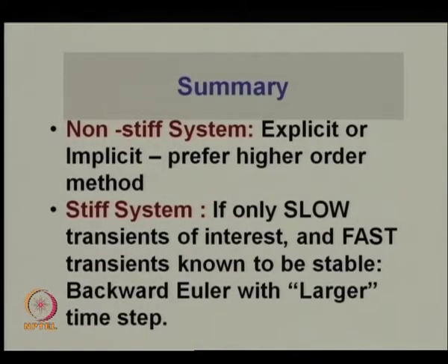So, to summarize this part of the lecture, for a non-stiff system, there is less of a worry that the system will become unstable if you choose your time step appropriately. Appropriately in the sense that if you know something about the system, you can choose your time step roughly to correspond to the fastest time constants in your system. So, if it is a non-stiff system and you know that this exponential rate of change or the sinusoid is roughly going to be in this range, then you can actually choose a time step, use any method.